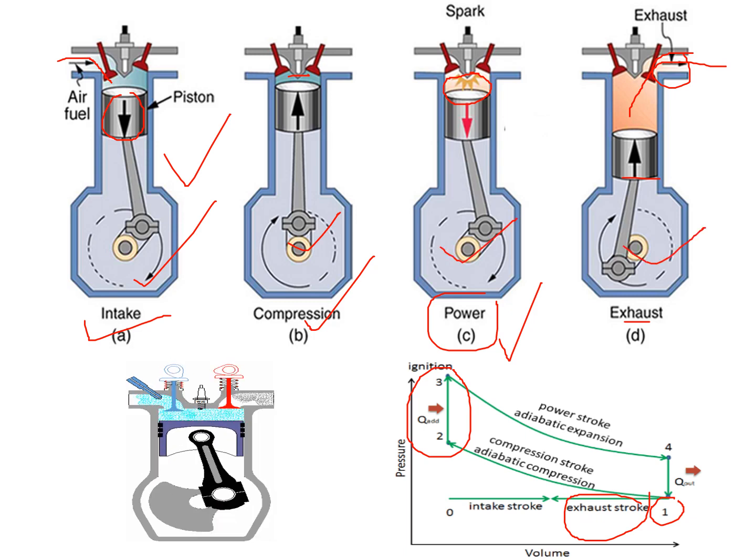So mainly we have the 4 strokes: intake or the suction, compression, power or the expansion, and the exhaust stroke. And these heat addition and heat rejection are very intermittent phenomena. This combustion is just at the end of the compression, and this heat rejection is just at the end of the expansion stroke. So these processes are also added in this Otto cycle to do the analysis of that particular cycle completely.